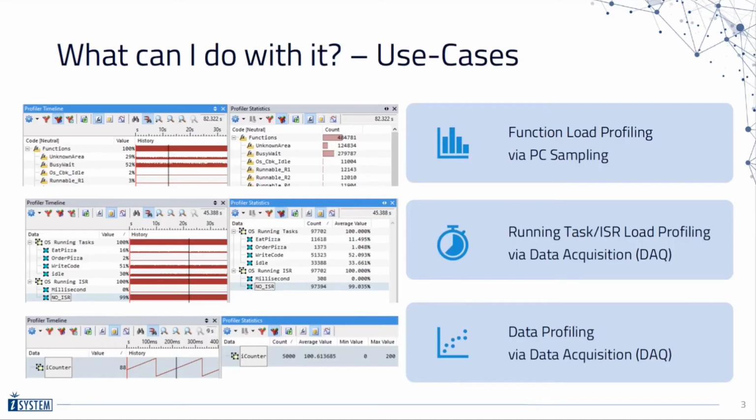What exactly does this information provide? What needs to be understood here is that we are sampling these values over time and not reading all the values, nor do we know when specific events happened. What we are providing is a snapshot of the program counter over time. This provides a statistical load analysis over time, not a real-time analysis of execution. This also depends on how frequent the system can sample the PC register. The higher the sample frequency, the greater the accuracy of the load analysis.